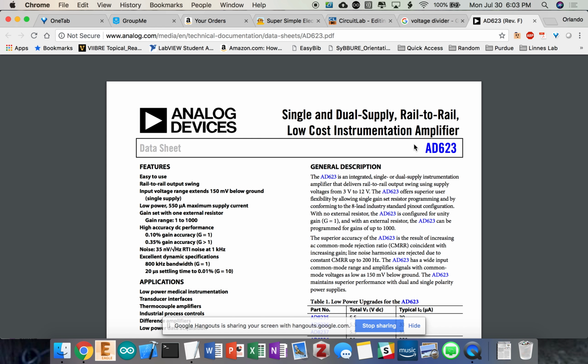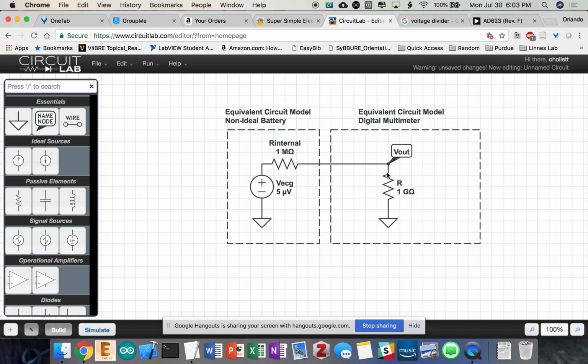So, quick question on the voltage part. Go for it. So, why do we put that massive second resistor there? Is it to like make the current basically dissolve to nothingness after it's read, or? Yes. So in this case, I'm trying to measure the exact voltage of a battery. So I want that resistor to be really, really high.